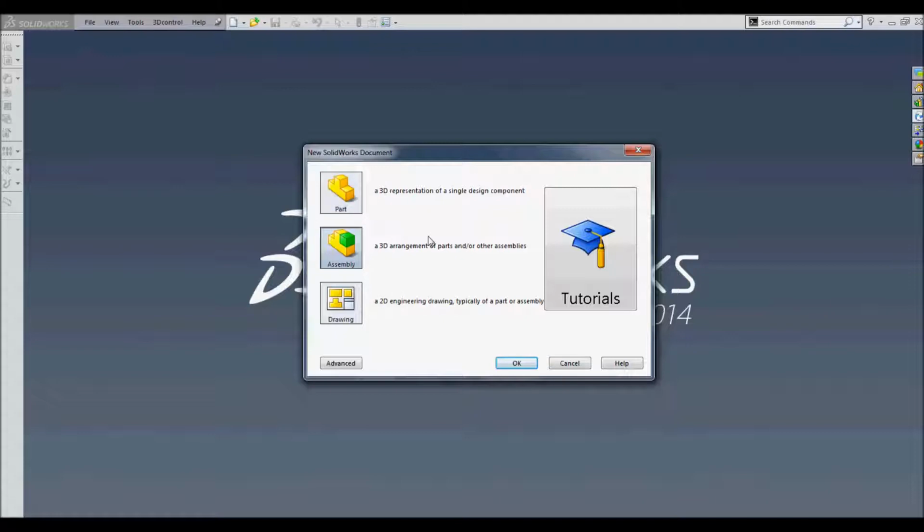Next up, we have the assemblies. The assemblies will typically take parts and constrain them together through the use of things called mates. Mates can be done in many different ways, but essentially the assembly will take your parts and it will allow you to make an entire structure with them. So it's extremely useful. You can also use sub-assemblies inside your assemblies, which is especially useful if you're making very large assemblies, which is what we do with our master assembly with the car, because it allows the program to run slightly faster.